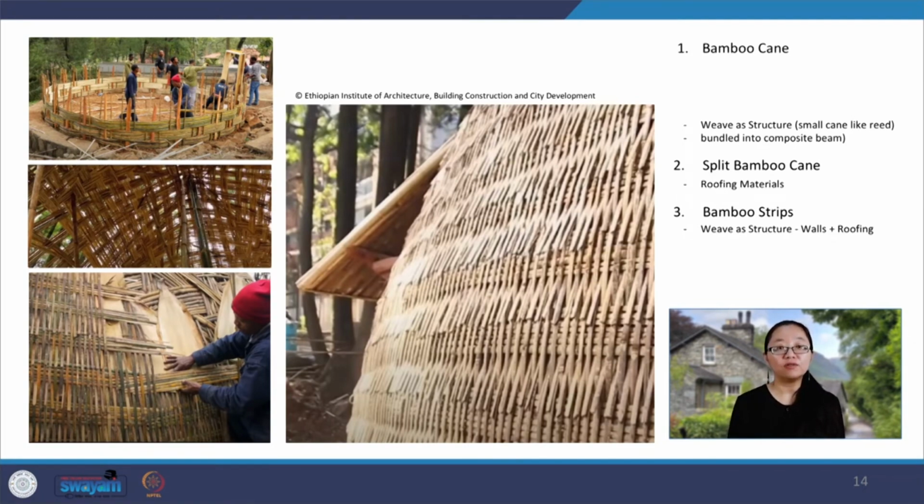The construction of the walls is made by splitting the bamboo to smaller strips and use whole bamboo with smaller diameters and then weave them from the bottom up until midways. Then, a sheet of unfinished woven bamboo is placed on top, followed by weaving the top and bottom part together. In the process, they use a pole in the middle of the interior to support the top dome.